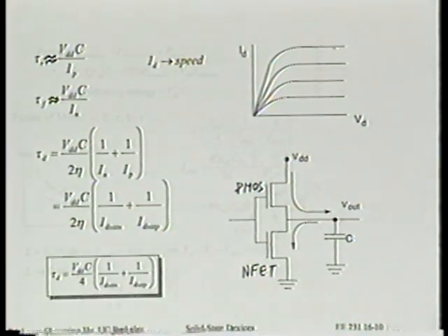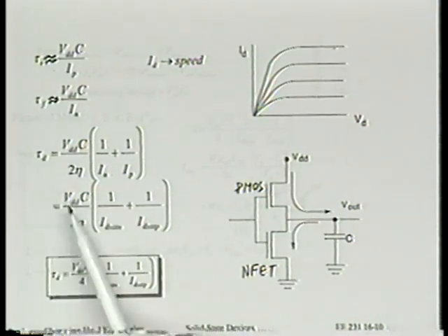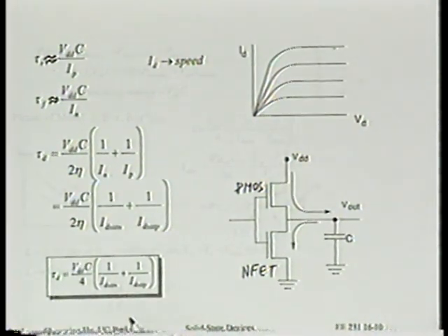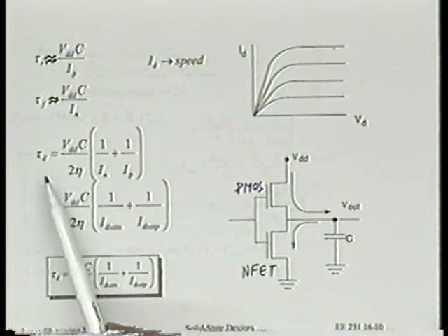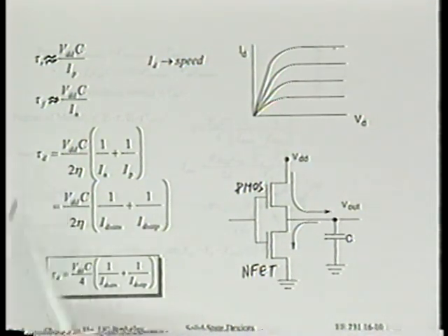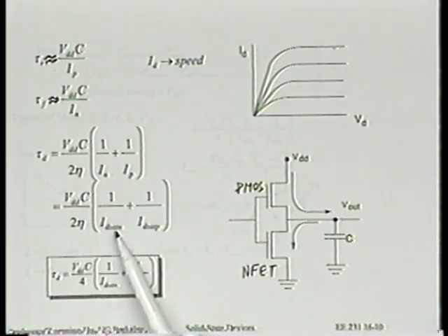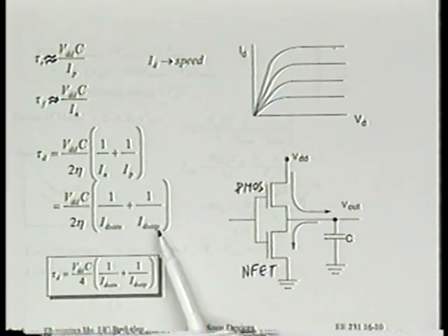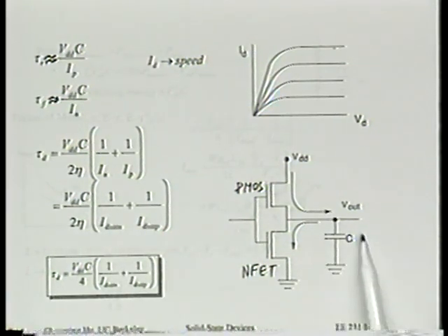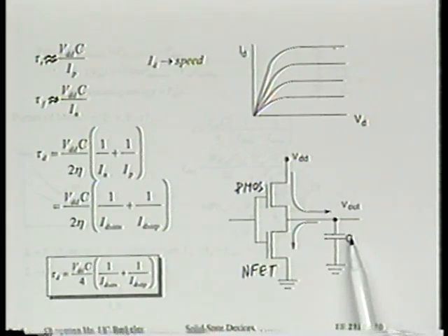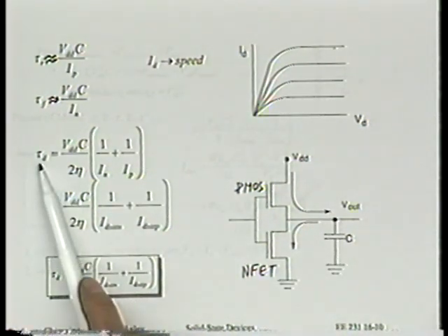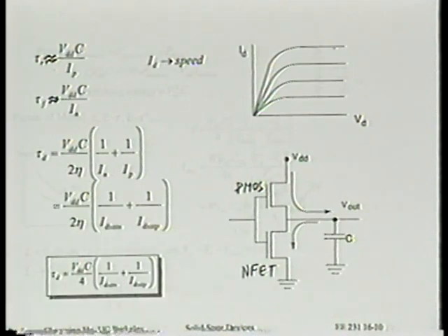And then we compare this relationship with SPICE simulation. You can easily construct some sample circuit for SPICE to simulate the delay time, simulate some ring oscillator delay times. Very easy, right? Because you perform the SPICE simulation, you can also plot out the SPICE model to see what ID set N is and ID set P is. You see what I'm saying? If you know the ID set, you know the capacitance you put on in your simulation circuit, your load for your ring oscillator, you know the VDD used, and you simulate tau, then you can figure out what eta fits a broad range of the circuit you simulate.